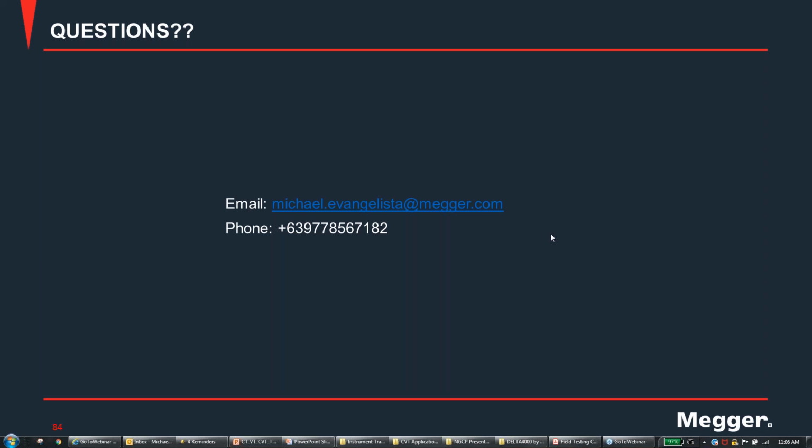If you inject on the secondary side of a VT, there could be a voltage transformation on the primary side, and you might produce a high voltage there. Imagine you have 13,000 volts to 115 volts on the secondary, and you inject 115 volts on the secondary, that can produce 13,000 volts on the primary. That is very unsafe. That's why when we do the VT or PT testing, we do a step down and inject on the primary side, not on the secondary side.